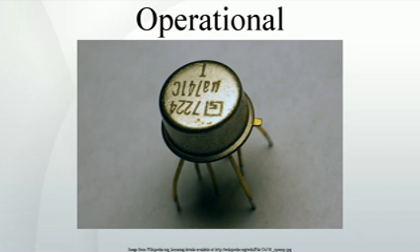These ideals can be summarized by the two golden rules. The first rule only applies in the usual case where the op-amp is used in a closed-loop design, negative feedback, where there is a signal path of some sort feeding back from the output to the inverting input. These rules are commonly used as a good first approximation for analyzing or designing op-amp circuits.